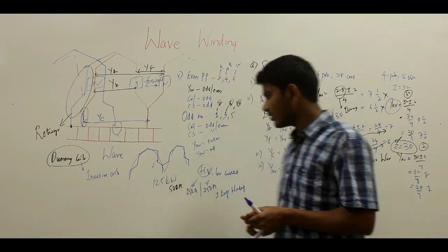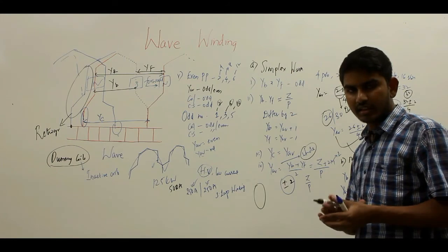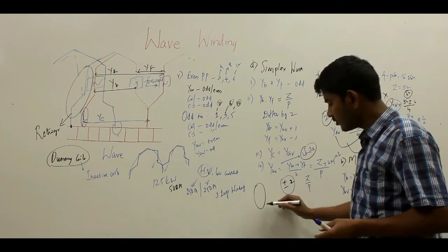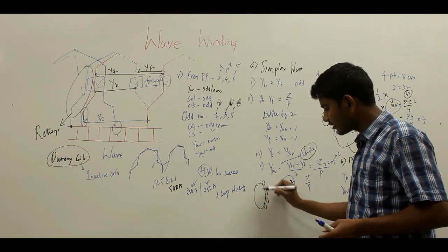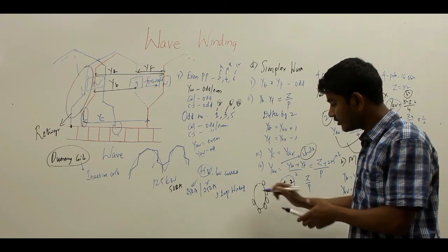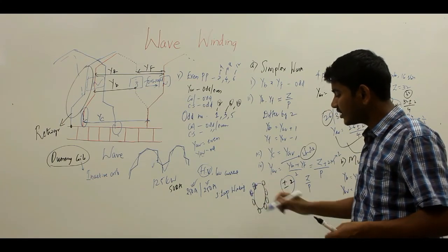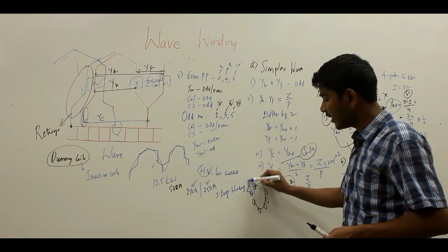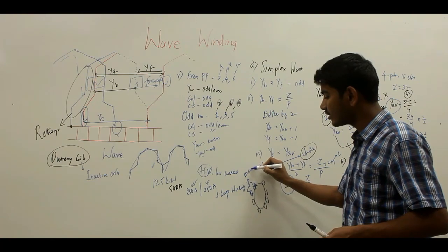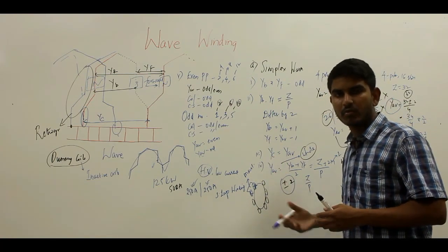So as you can see, there are 6 conductors useful and 2 conductors are not useful. So you will be having 6 conductors, 1 2 3 4 5 6, and these 2 conductors will be isolated electrically, and these 2 conductors will help you in maintaining the balance of the machine. Now if you do not employ these 2 conductors, then your machine won't be balanced.